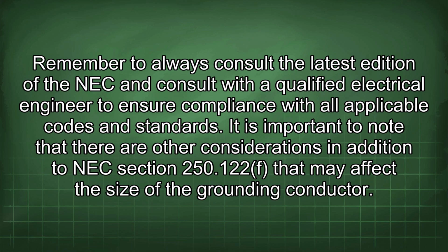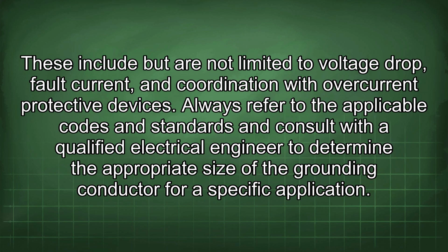It is important to note that there are other considerations in addition to NEC section 250.122 that may affect the size of the grounding conductor. These include, but are not limited to, voltage drop, fault current, and coordination with overcurrent protective devices. Always refer to the applicable codes and standards and consult with a qualified electrical engineer to determine the appropriate size of the grounding conductor for a specific application.